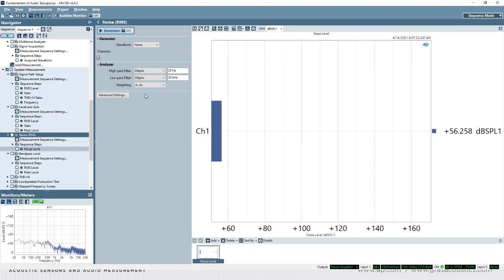I will say this: if you stimulate a device that is perfectly linear and time invariant, a cable, for example, with white noise, the FFT of that will be a straight line. But it depends on your test signal, and on how you deviate from that and what the behavior of the device is.